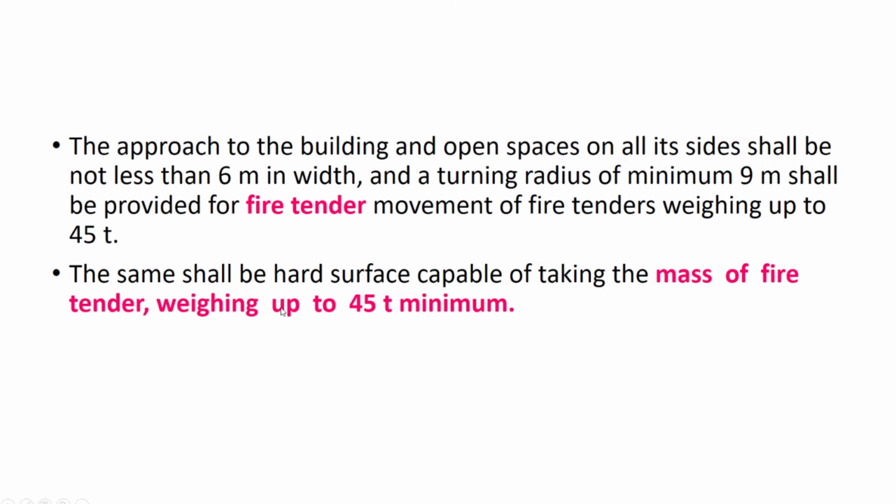Because many times the consultant may not be aware of the changes which have been made in the IS code in the recent past. For structures and buildings having any of the plan dimensions exceeding 50 meters, so it's a long building. For again multiple buildings in a site covering an area of about more than 0.4 hectares.